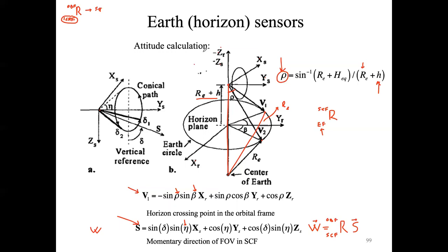Okay, so the question is, if we have already three components, to determine the attitude of the spacecraft, here V1, would those not be sufficient to determine all those parameters? Well, the answer is no, because basically, first of all, these vectors, in order to be well known, should be unit vectors. So you have a degeneracy because basically one of the components is fixed, because you are assuming that you are using unit vectors.